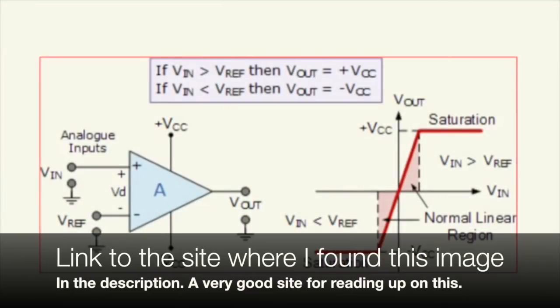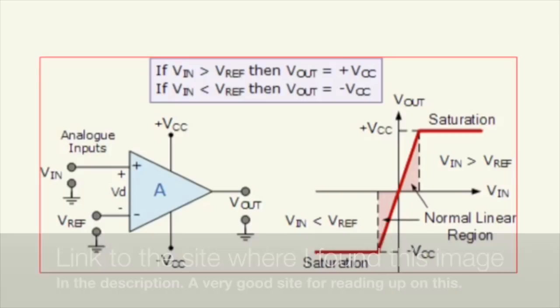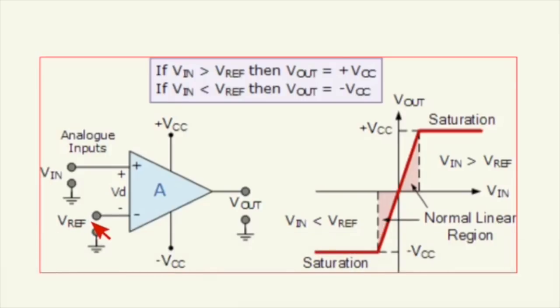This is a really good picture of the OpAmp Comparator. Down here, on the inverting input you have the voltage reference input, and on the non-inverting input you have the voltage input of whatever signal you want to compare to the reference signal. When voltage in is higher than voltage reference, then V out is equal to voltage plus. If it's lower than voltage reference, then voltage out is voltage minus.